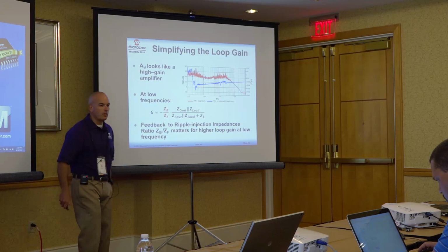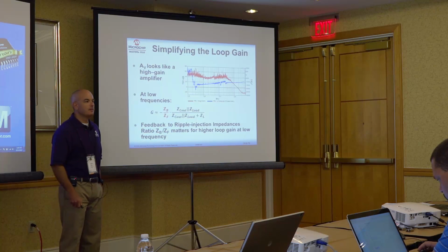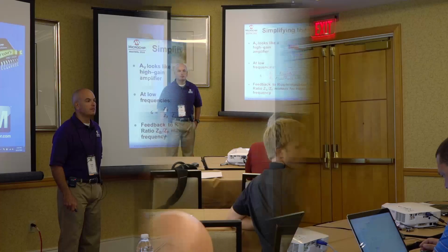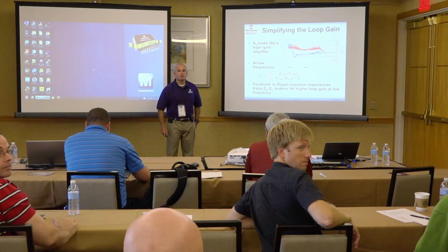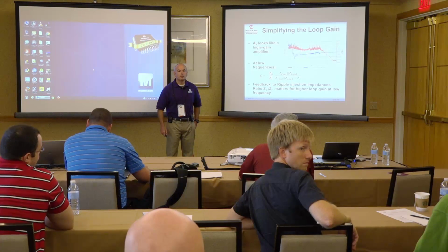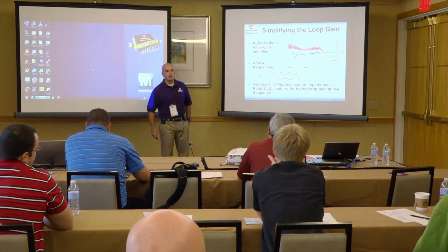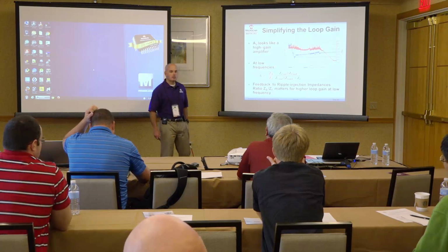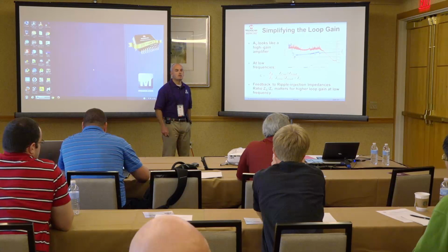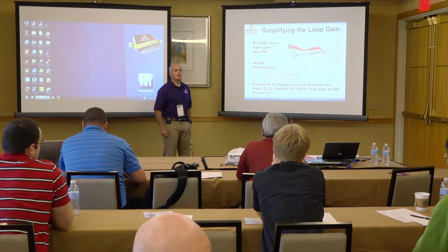I answered your question. Would that imply that the best response is achieved without any ripple injection, relying strictly on the output ripple? When there is no ripple injection, ZB is infinite, right? So you get the highest gain.